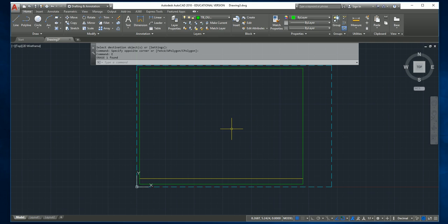So the next thing we kind of want to do is we're going to create text inside of the title block, but it's not normal text. Normal text, you have to edit piece by piece by piece. But because we're creating a block that's going to come in, we're going to give it an attribute so that when you enter it in the drawing, a prompt will come up and say, hey, what is this? And it'll give you a description of what it is.